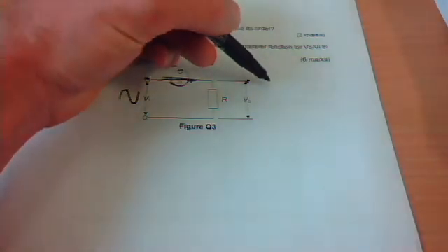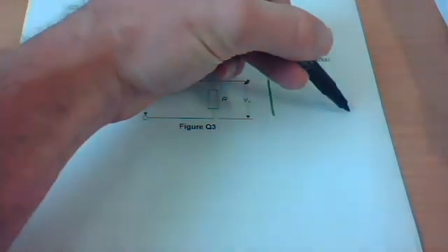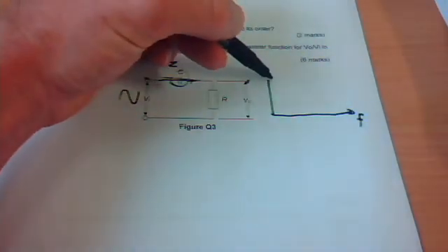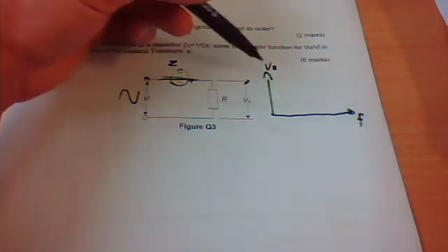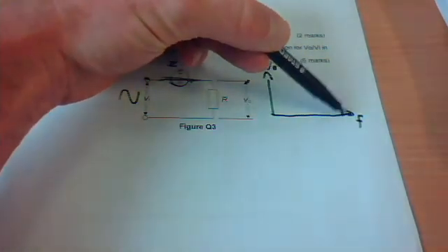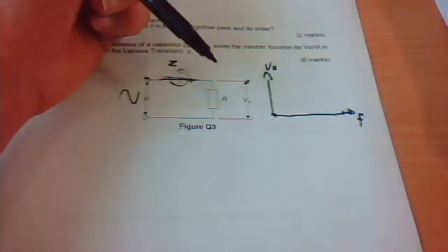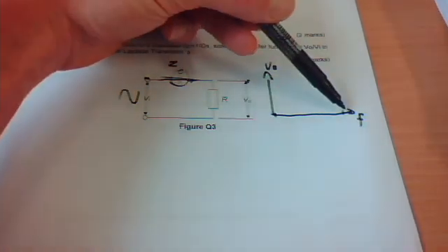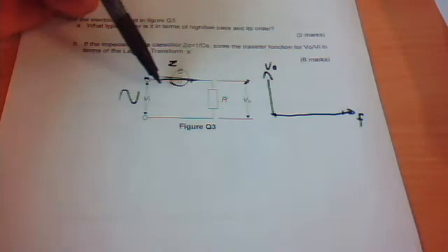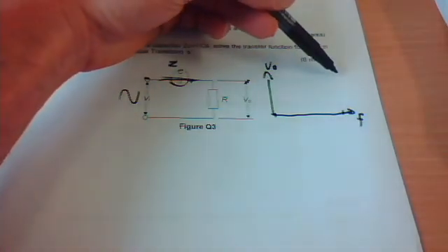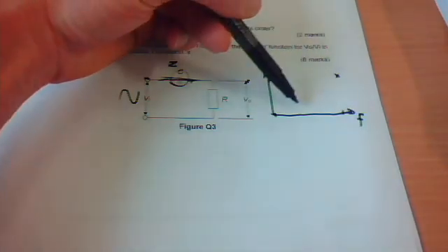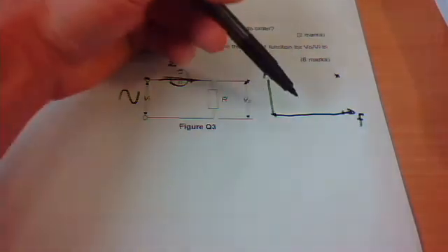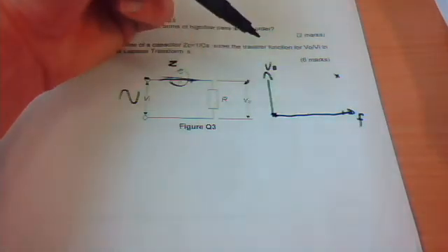So visualizing it as a bode plot, now you might remember a bode plot is frequency on the x-axis and voltage output on the y-axis. Then we can say high frequencies are plotted here, low frequencies are plotted here. So a high frequency means that the output is the same as the input. In other words, it will be a large value. And for a low frequency, we have an open circuit pretty much, so we've got almost no voltage.